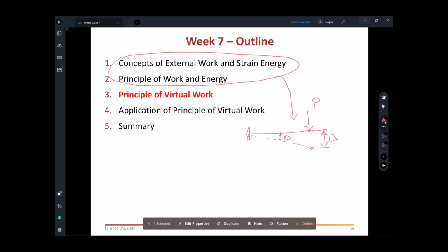It was easy, nice and smooth to explain. It can be applied for beam, it can be applied for truss, even for frame. Methods 1 and 2 were very good, and I like those methods as well. But the big limitation is that it can only be used to find the displacements where the load is applied. You got my point? So these methods 1 and 2 that I just explained in the first 42 minutes cannot be used in most places, because you do not always tend to find the displacements where the loads are applied.